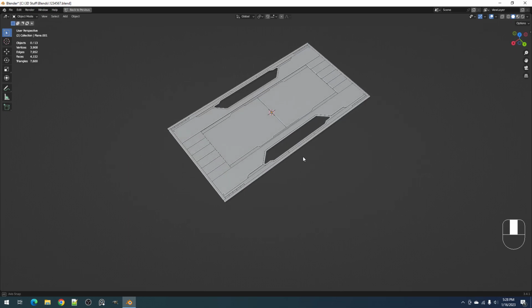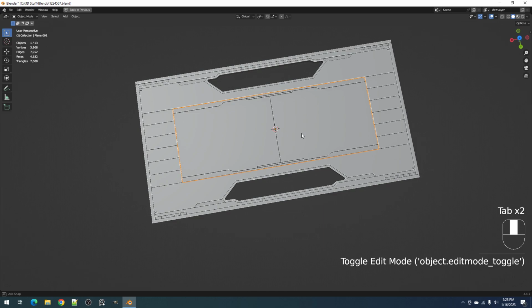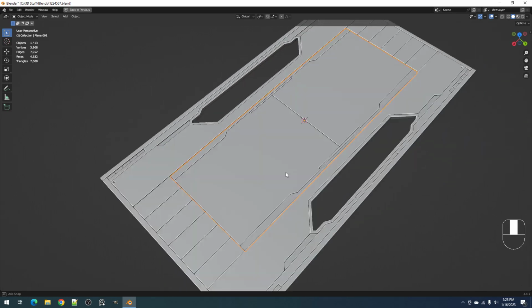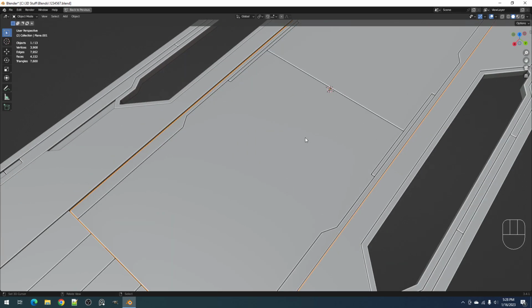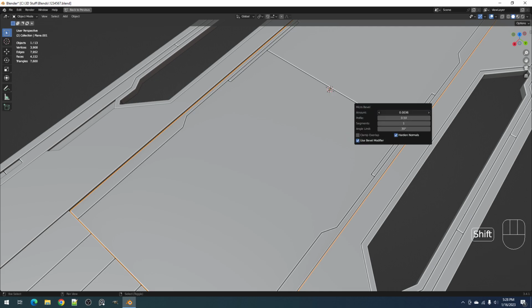Same with things like character armor. If you're gonna use this for panel cut details and just bake the normals, you can of course do that. Just be sure to use the bevel modifier. To make it more apparent to the bake engine, you can of course increase the amount on the bevel.